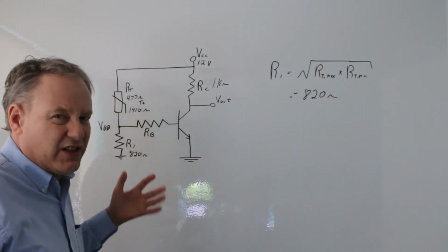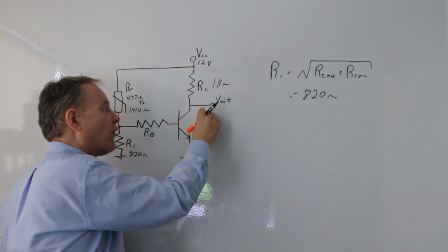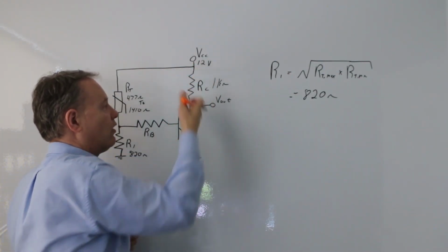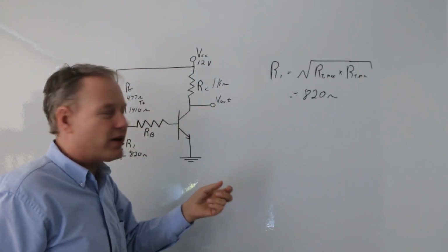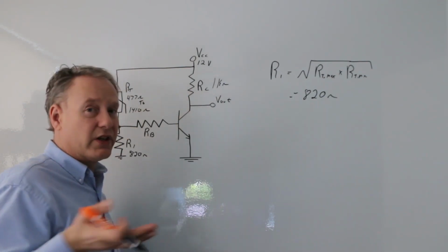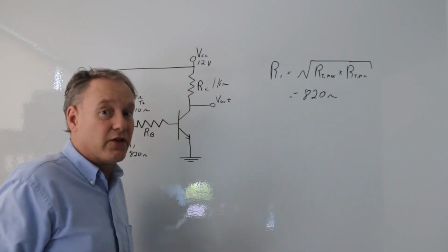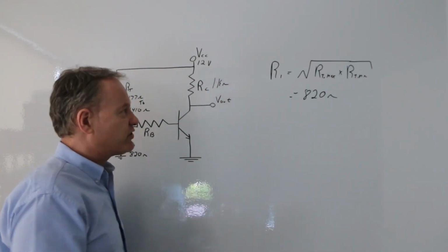And that'll be fine. Even if it's small, it's still drawing current. And then this thing will be closed, and that voltage will be either 12 or 0.2. Again, we don't care how much current we have out of here. If I put a 1K in there, I'm definitely going to have enough current. It'll be really small, but it's fine because the Arduino doesn't need very much at all. So with that said and done, I'm going to put a 1K in there.